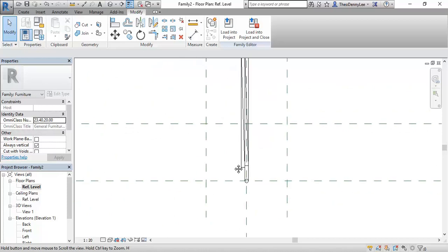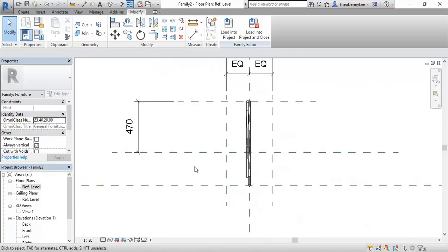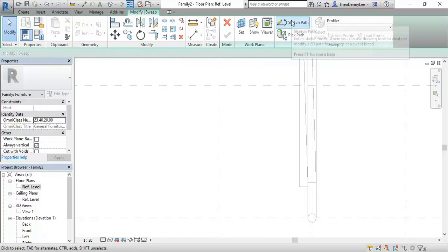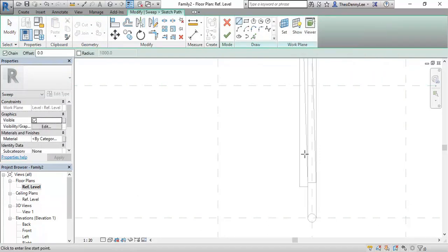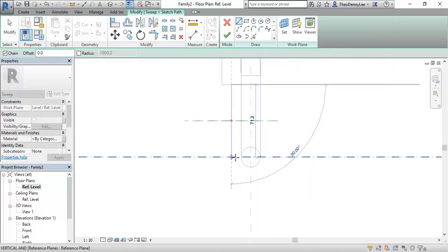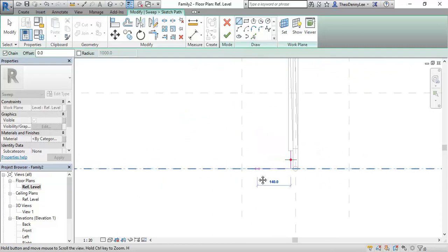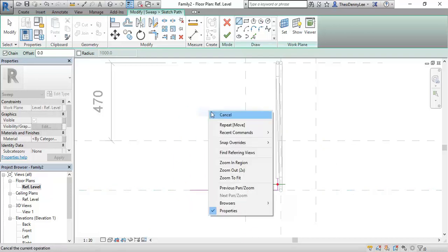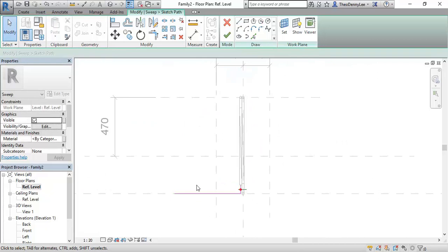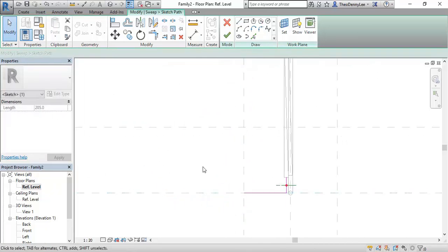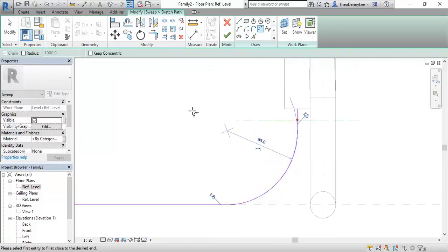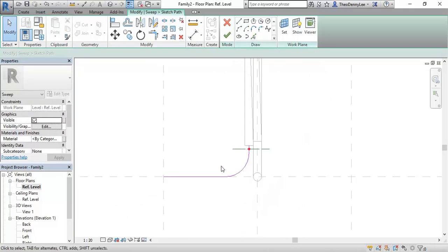But here, though, I can go into the top view and make a new sweep with, again, sketch path, starting on the end of the shape I've just done, and coming across. Now, I can't go too much further than that because I want to do some nesting in a moment, but I'll just finish this shape with fillet, and that should give you the basic most important concept, which is drawing sweeps in different planes.